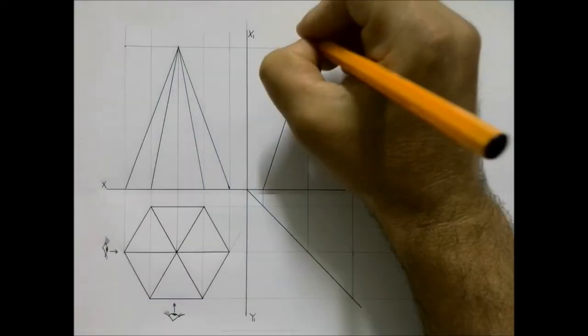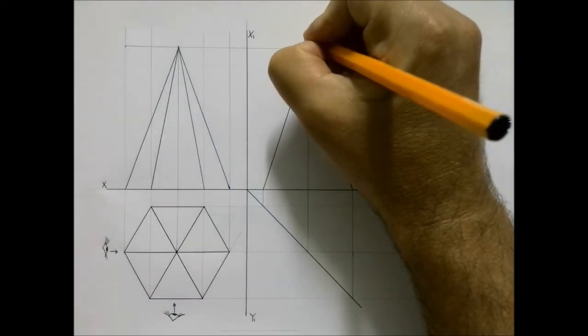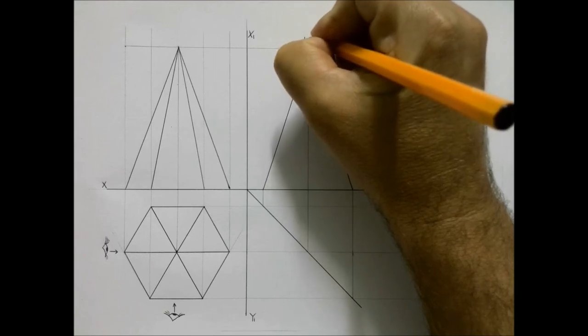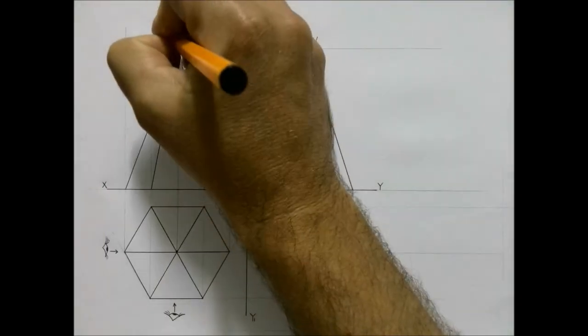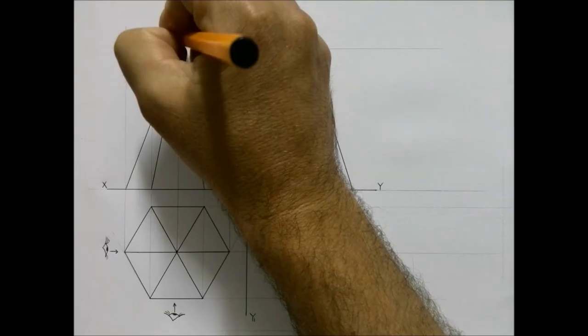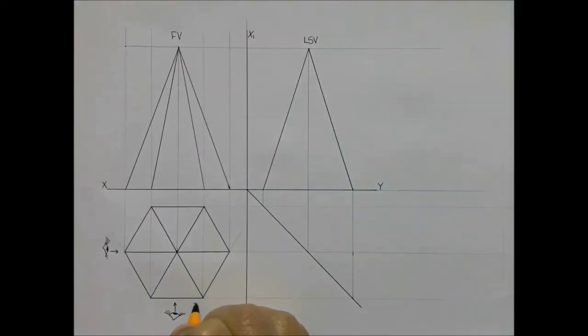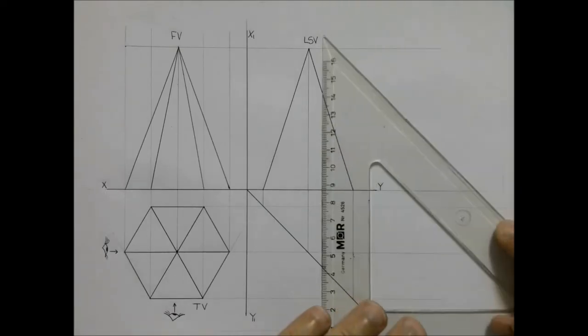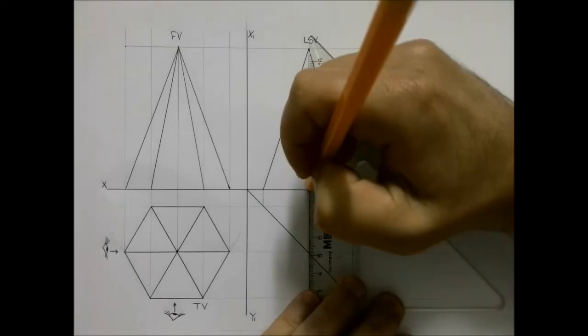Right, so this is first angle orthographic projection. So this will be my left side view, this will be my front view, and this will be my top view. You will obviously do them between 4mm guidelines to keep it nice and neat and to a standard. Right guys, let's just quickly include the middle line. It's not a construction line.